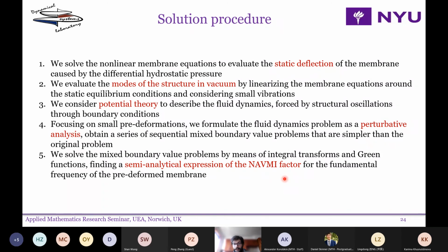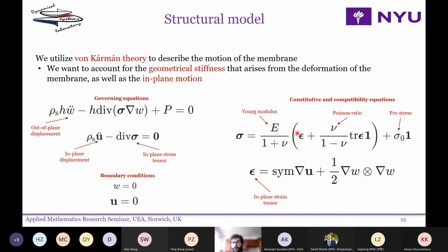In particular, we focus in this case only on the fundamental frequency of the pre-deformed membrane because it's the one that we saw has the most impact in the experiments, but it can in principle be applied to any mode. So for the structural model, we utilize a von Karman theory to describe the motion of the membrane. In particular, we want a von Karman theory because it's a relatively simple theory that accounts for both the geometrical stiffness that arises from the deformation of the membrane, as well as the in-plane motion that can have an impact on